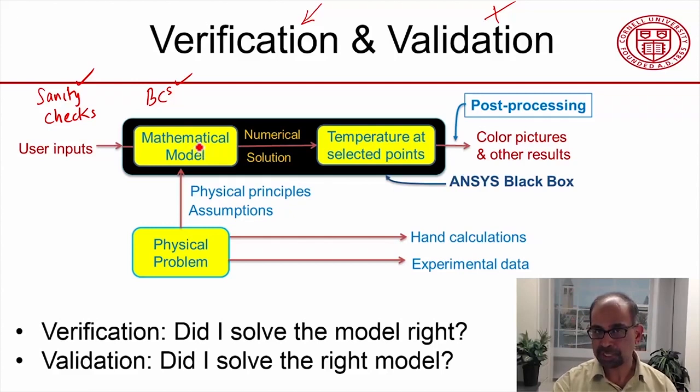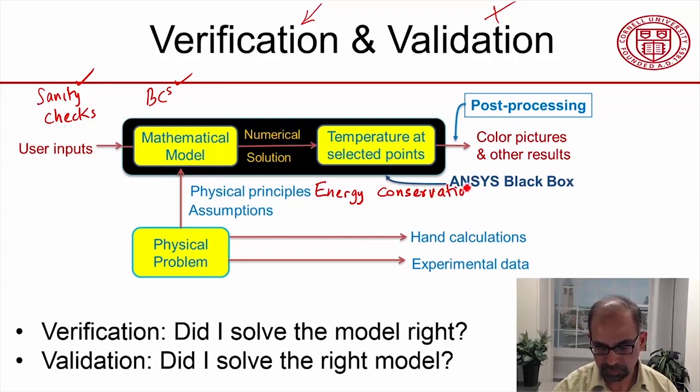The physical principle contained in the governing equation is energy conservation, or energy balance. So we can check if the results are consistent with that principle by checking the reactions, as I talked about in the big ideas in FEA.